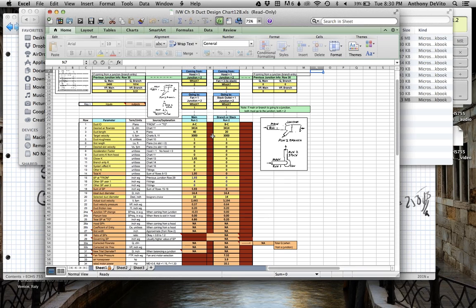So I'm saying this is not something all that hazardous. Where he's working, a foot away from this hood, handling these solvents or spray painting, or doing some other activity, I want 100 feet per minute velocity pulling that away from him. If it's a really hazardous material, I might want a higher velocity than that.